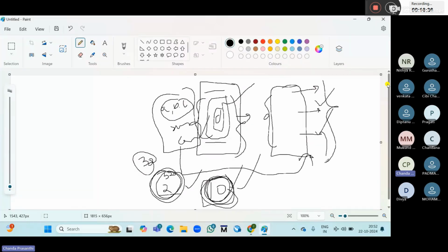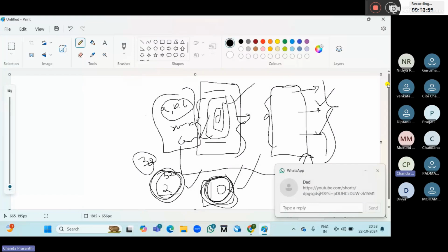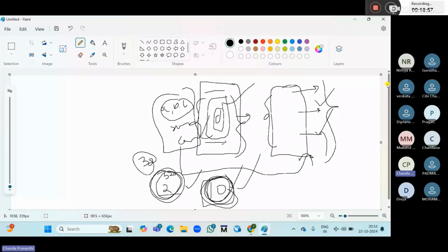It checks whether we met the design functionality or not, whether we verified the total functionality or not. To check that we use the coverage, and to check that we use the test benches. Whatever test benches and tests we have written, whether they are doing their operation or not, whether they are used to hit all the functionality or not, to verify that, we write the coverage.